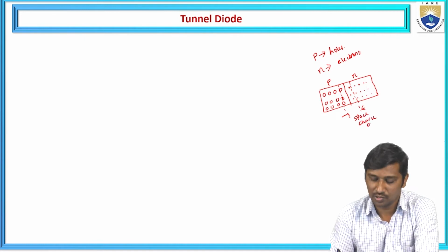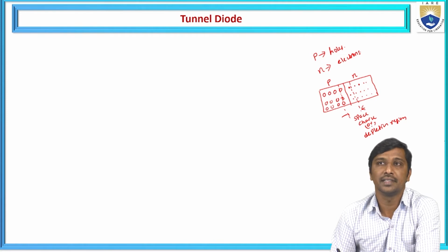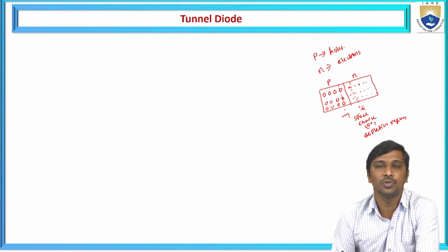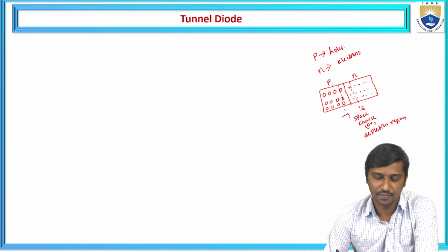It is also called the depletion region or space charge region. Then, if we want to allow conduction across the PN junction diode, we need to apply biasing to it, to observe how the charge carriers diffuse from one region to the other to allow conduction in a PN junction.